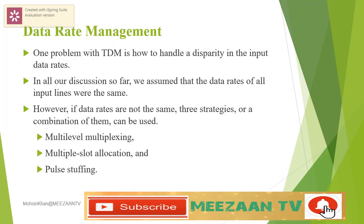The main problem with TDM is how to handle a disparity in the input data rates. In all our discussions so far, we assumed that the data rates of all input lines were the same. However, what to do if data rates are not the same? Three strategies, or a combination of them, can be used. We call these three strategies multilevel multiplexing, multiple slot allocation, and pulse stuffing, as shown in the figure.